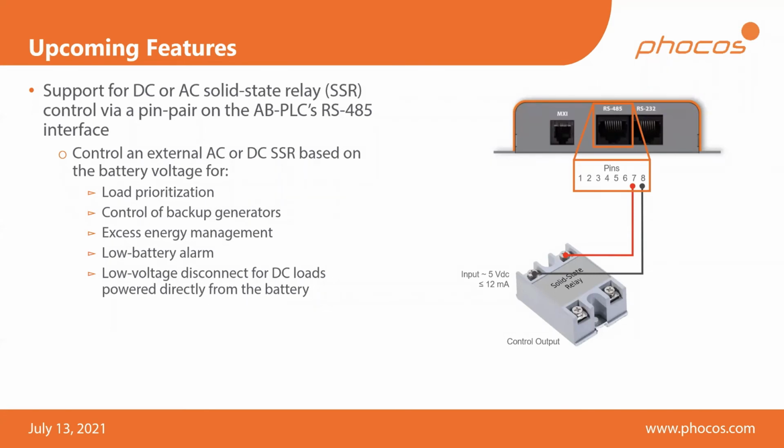If you want to differentiate between those, so that if you're in a low power situation, maybe there's not a lot of PV power coming in, maybe the grid has failed, you don't have a genset, or you don't want to use it because it costs a lot for fuel, then you want to make sure that you're turning off your low priority loads well before the whole system essentially needs to turn off because the battery is depleted. So load prioritization will help you do that.